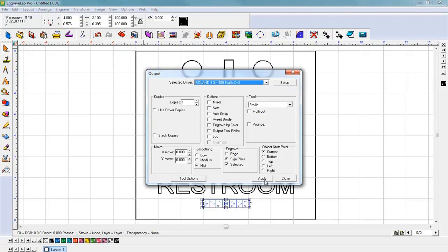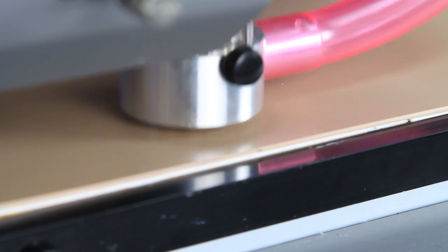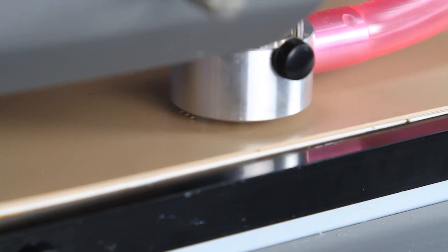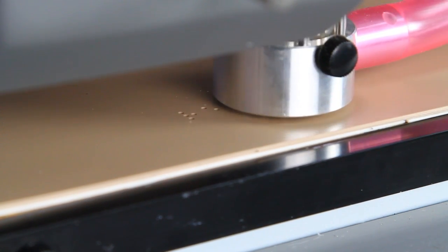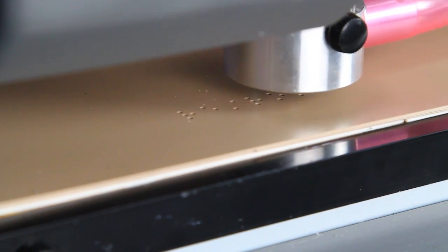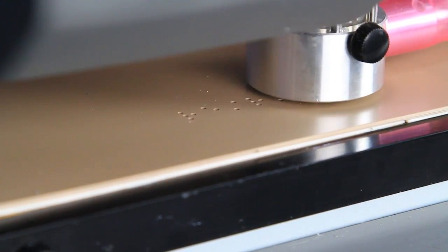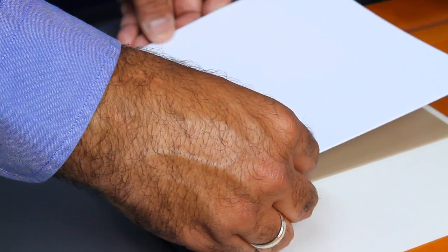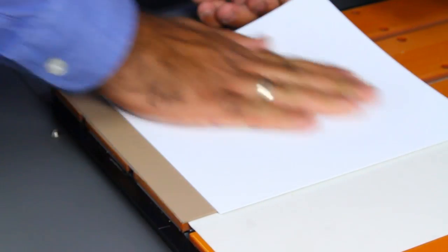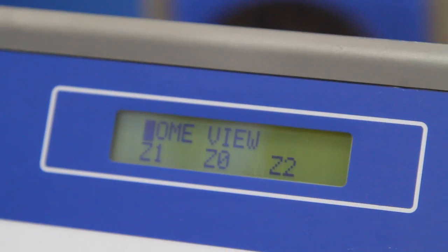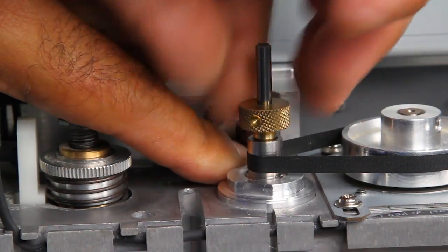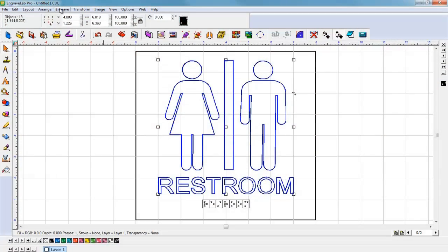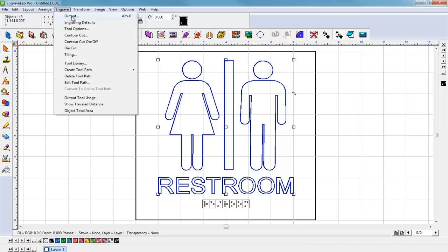Now you can begin engraving the Braille portion of the sign using the Braille drill cutter. Next, place the adhesive back tactile material into position on the substrate. Once again, move the carriage into position. When this is completed, replace the Braille drill cutter with the character cutter. Output the file and the EGX will automatically route the text and pictogram.